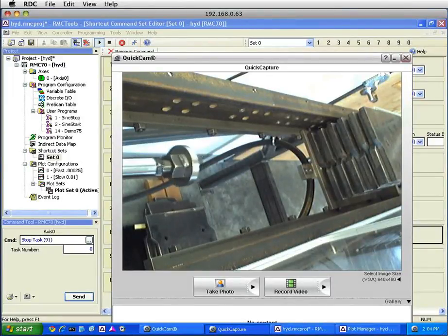Hello, this is a video of my hydraulic system doing a 2 Hertz sine test. You can see in the picture I've got a hydraulic actuator going back and forth. The amplitude is 1/2 of an inch, or about 12.5 millimeters, and the frequency is 2 Hertz.